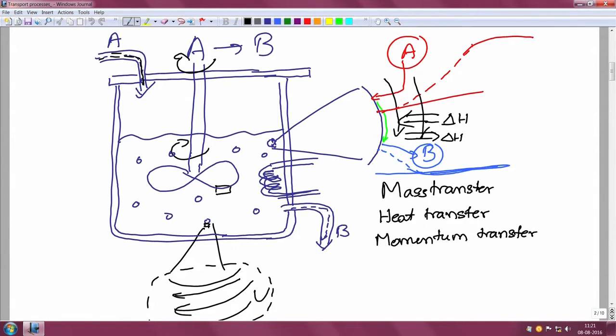there are particles on which the reaction gets catalyzed. And I had tried to explain to you that it is not sufficient to ensure that enough raw materials are put into this reactor, enough products are taken out of the reactor, there is enough heat that is supplied or taken out of the reactor. It is also necessary at the microscopic scale, at the particle scale, to ensure that where the reaction takes place, there is a sufficient flux of reactants to the surface locally. Okay. And this flux is determined by a variation in concentration close to the surface.